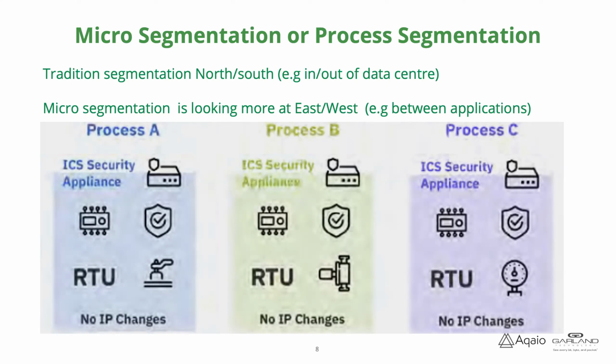So coming back to what I said earlier, the language of the industrial environment needs to be recognized as well in those relevant things. So Modbus, DNP3, OPC, you name it, we need to recognize that going through. And then after that, we need to do deep packet inspection inside there.